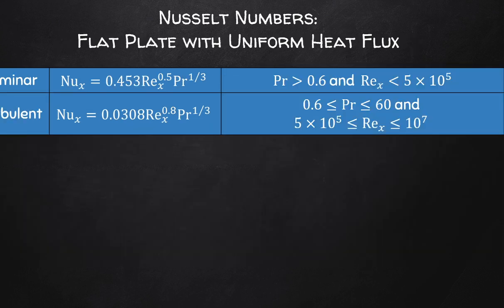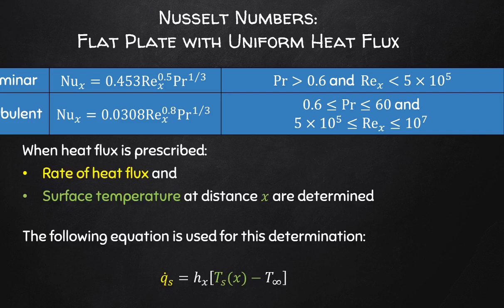In the case where there is a uniform heat flux, okay, so the previous equations were for isothermal flux, isothermal temperature. If you have instead a uniform heat flux throughout the length of pipe, the following equations apply, where instead of you having an isothermal temperature given to you throughout, the rate of heat transfer is given instead with the surface temperature Ts, and obviously Ts will change due to changes in heat, the convective heat transfer coefficient.